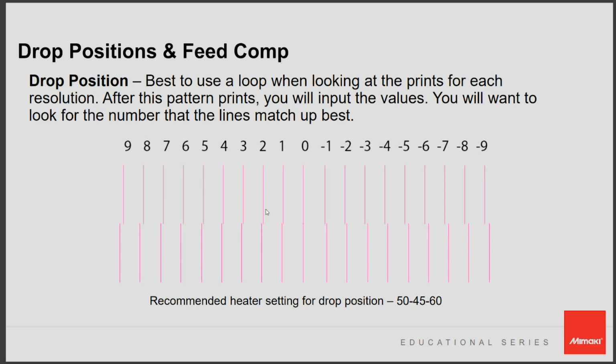Ideally, when you get your machine installed and the technicians do their machine alignments, it will be 0. But over time, it may shift to maybe -2 or +3, depending on the thickness of the material you have or just time in general. So this is a very, very simple way to readjust your alignments. I do this all the time whenever I'm testing new material or changing material.